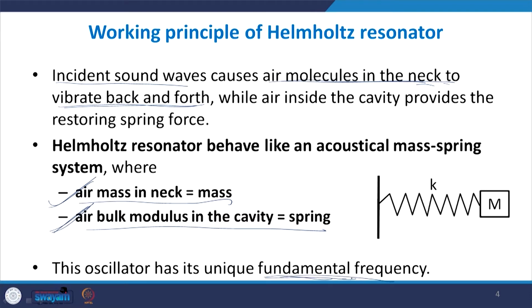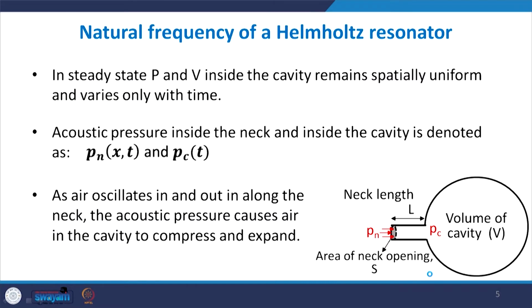So, let us find out what the fundamental frequency of this Helmholtz resonator is. In the steady state, we assume that the pressure and the volume inside the cavity are constant throughout. We are assuming here that the cavity is big enough compared to the neck. So, whatever addition or removal of air molecules takes place will still be small.